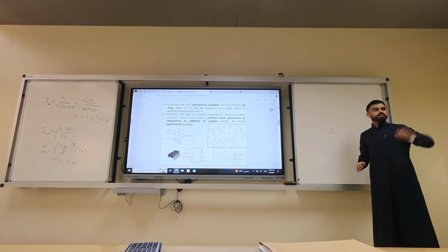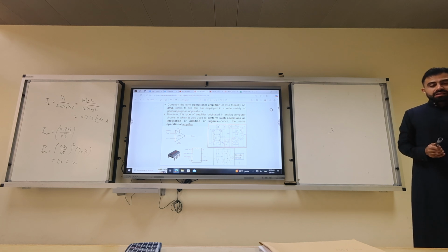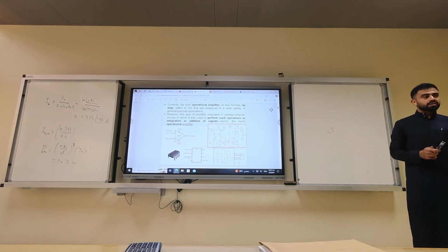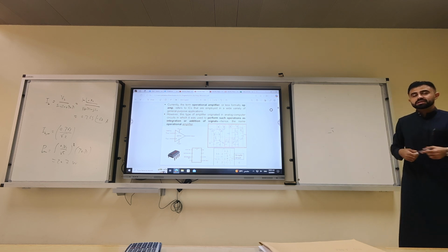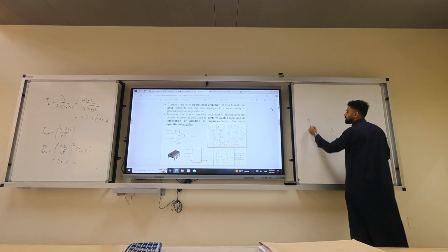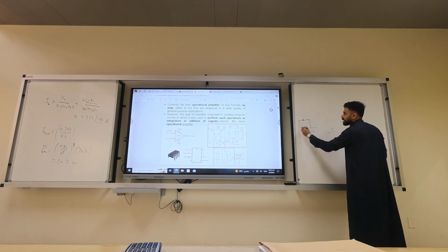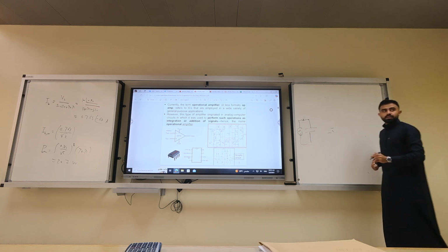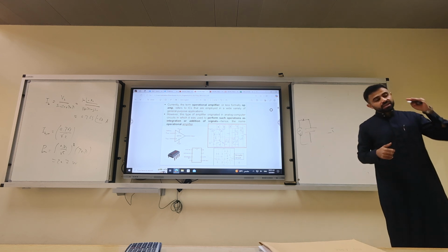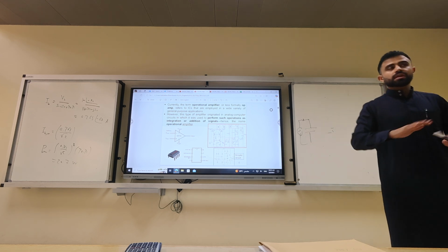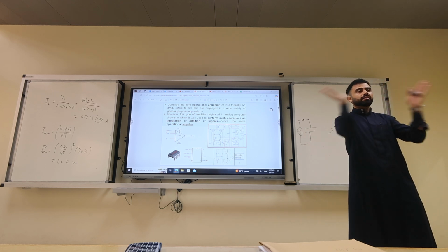Okay? Yes. So, Doctor, what's the main difference between the amplifier and capacitor? The capacitor does not subtract the difference. The amplifier subtracts the difference. The capacitor doesn't have any input. It's a passive device. You don't need to power it. You connect it to whatever system you have. No, it doesn't amplify. A capacitor, if you connect it to a DC, will store the voltage. That's it. If you connect it to AC, it depends on the phase angle, the phasors.